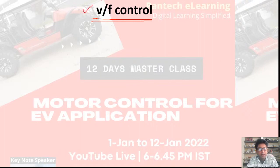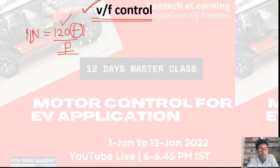So why is it called V by F control? Let us understand that and how it is done. So we know already the RPM is equal to 120 F by P. So the pole I cannot change and 120 is a constant. So the only way to change the RPM is to change the frequency, change the power frequency. So if I am able to do that, mathematically I will be able to control the speed.